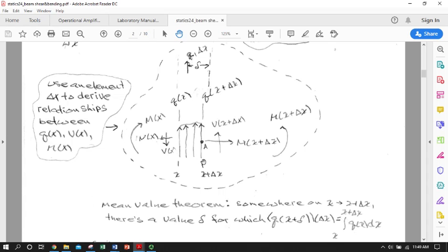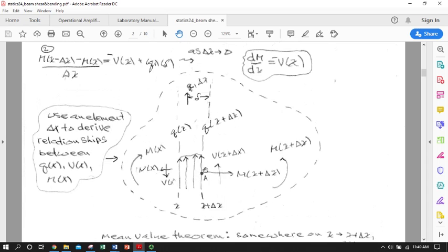Just like we did with the capstan equation, we're going to take that differential element and load it up, and then apply the conditions of equilibrium: sum of the forces in the x, the y, and the z. It's two dimensions, so we only have x and y, and then we're going to look at the bending moment about point A that's out there on the cut face.